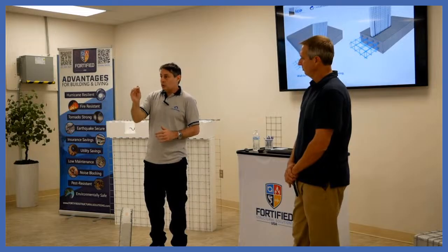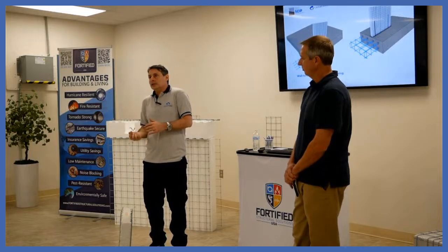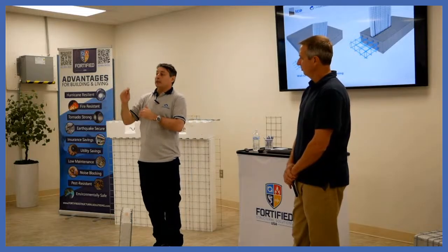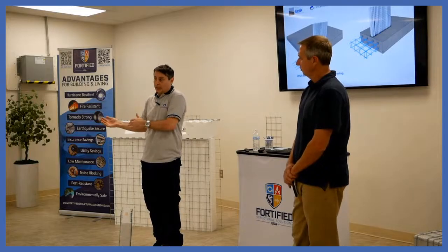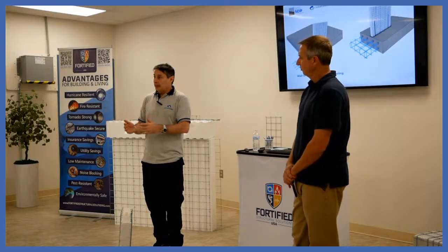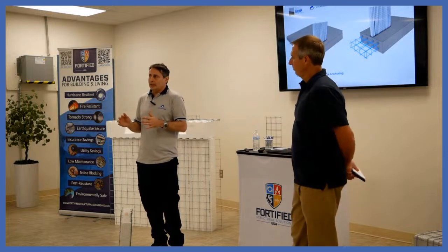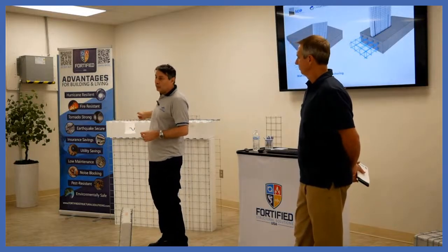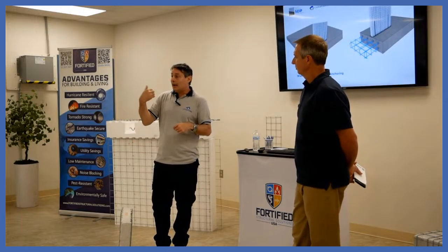You can choose, and there are options, as I mentioned. It's not like there's just one panel for that. You can use either a panel that is thicker but with fewer pockets, or some thinner with more pockets. It's up to you, and not just because; there are a lot of things involved. If you have more pockets, you need more rebar, you need more concrete. You probably end up having more cost.